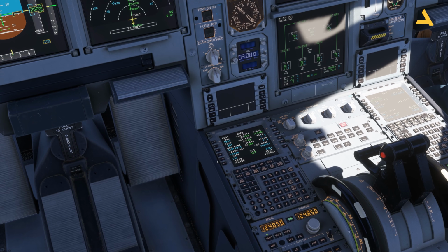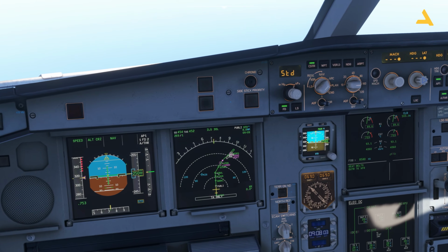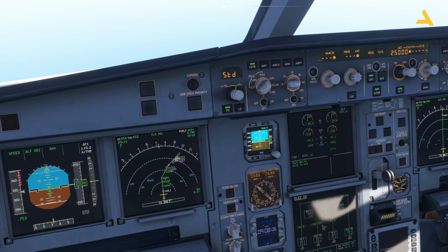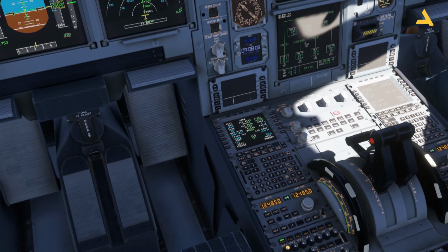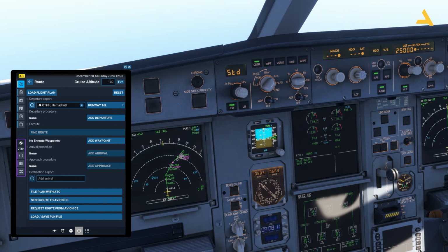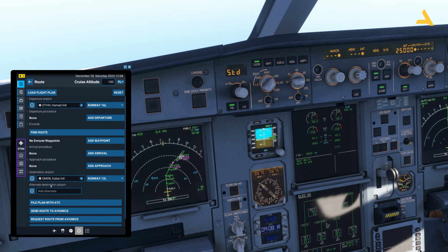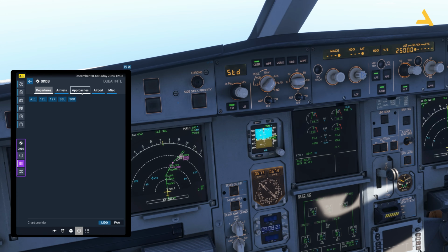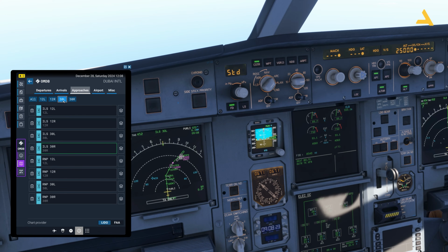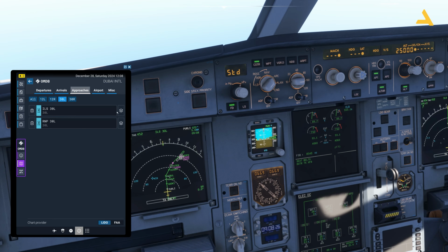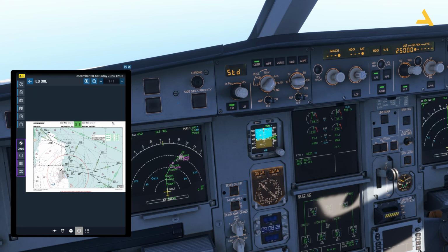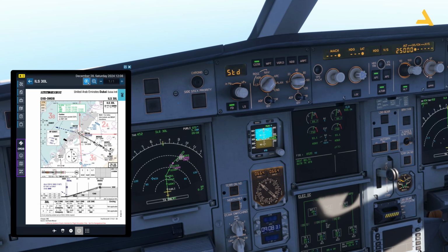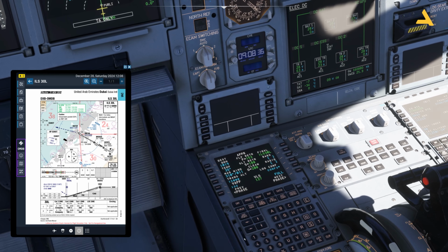That's it. And the transition altitude, it is an altitude at which I will be changing the barometric pressure from the standard to the given one, which is 1019. So let's open the EFB, and for Dubai International Airport, let's get the transition altitude. 30 left is the runway for the landing, and it will be ILS 30 left. So it is 13,000 feet. So let's enter 13,000.